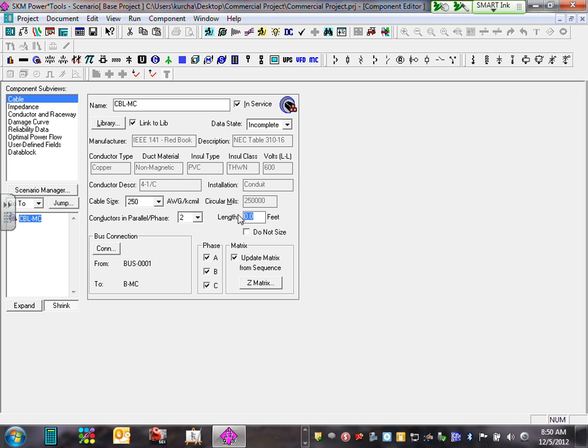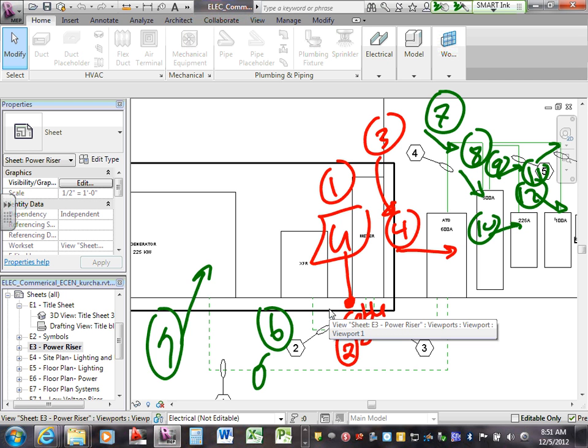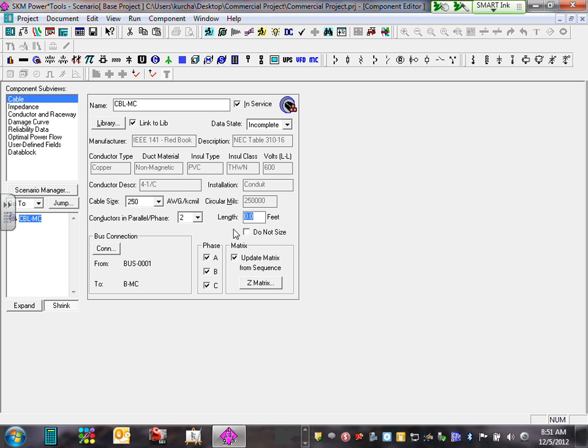If you look where they're located on the building, let's look at them. So you're going to do an approximation for the right here. So this is the cable that we're using, guys. From here, from the transformer into the box, right in here. Physically, they're located not far away from each other. I'm going to use 50 feet just for the heck of it. Otherwise, you measure it. So I'm going to use 50 feet.